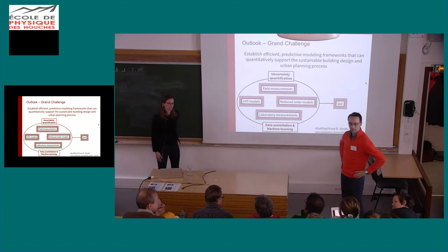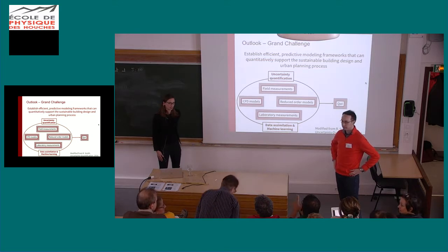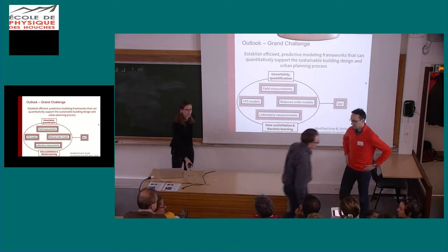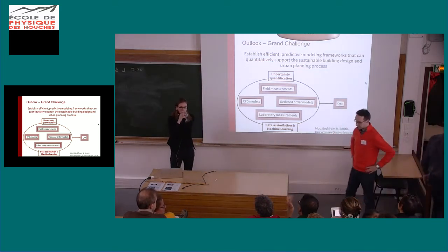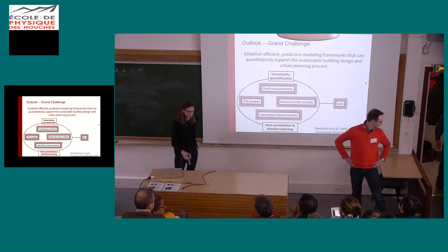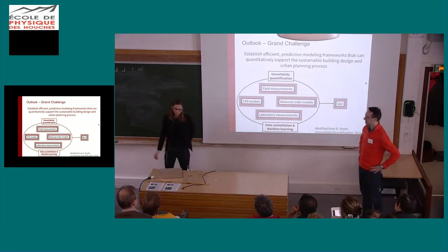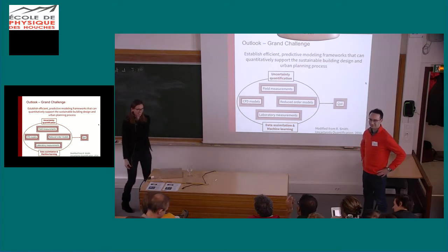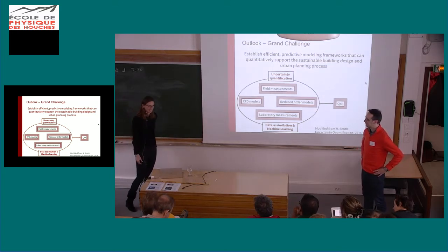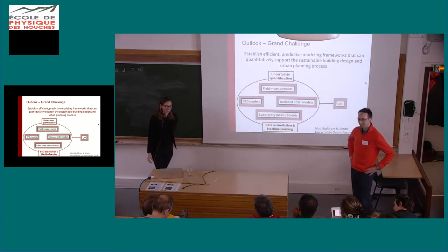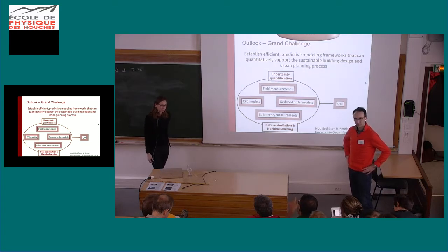So this is important in the turbulence model, right? One of your bullet points was, is any RANS turbulence model any better? You said none, right? And then during your uncertainty quantification, I noticed you used Menter's k-omega SST. Clearly that does well with flow separation. So is there an implicit bias already there that you have invoked in the analysis?